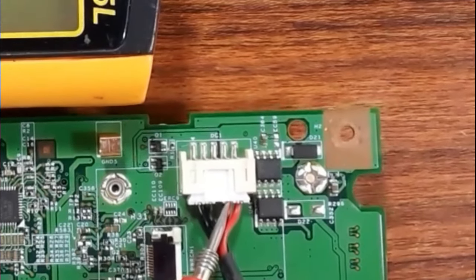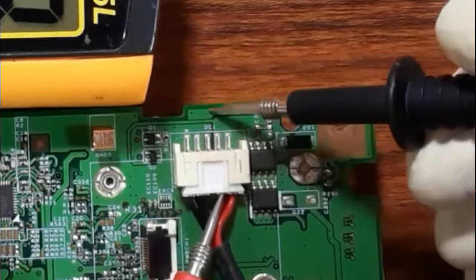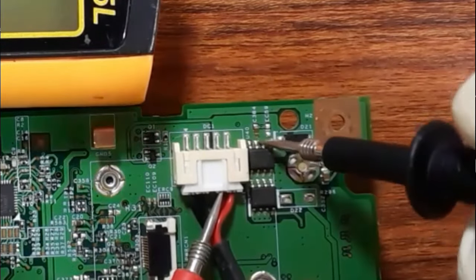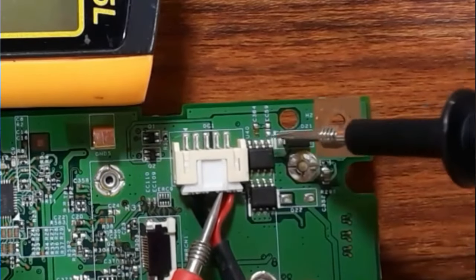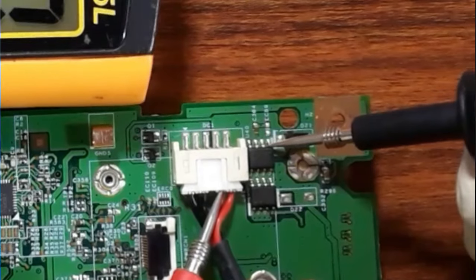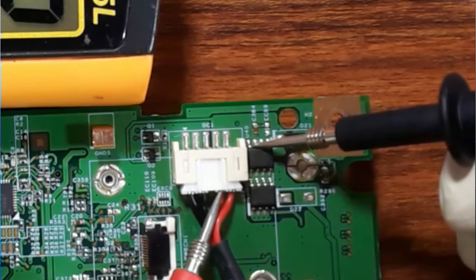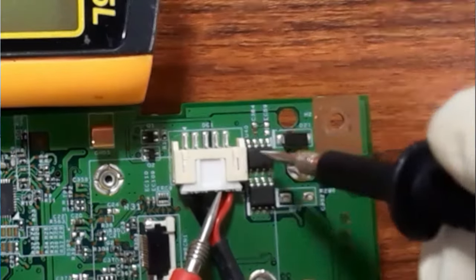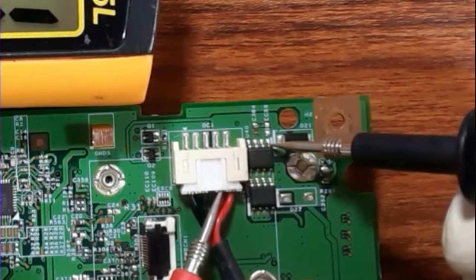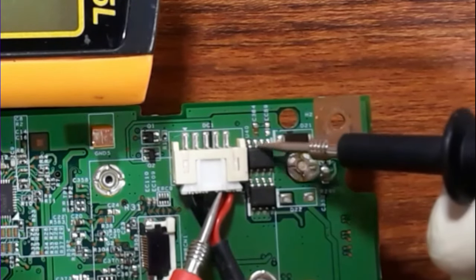So let's put one probe here and then go, as you see, this is we have a continuity, and then go, for example, to this switch, as you see. Okay, I have continuity here. So this is the first pin of this switch, this is the second, this is the third, this is the fourth. For the fourth, no continuity, means this is source. These three pins is the source of this MOSFET. So we have here source.